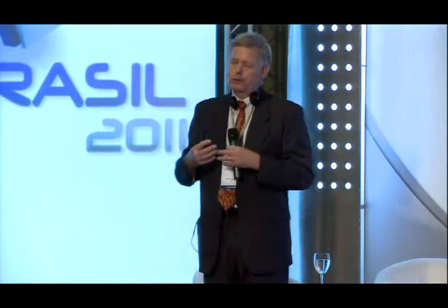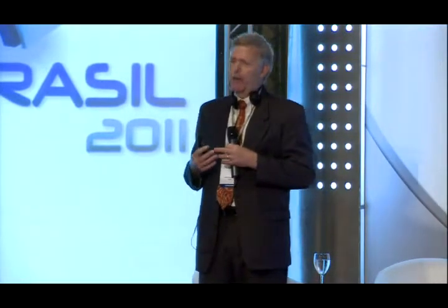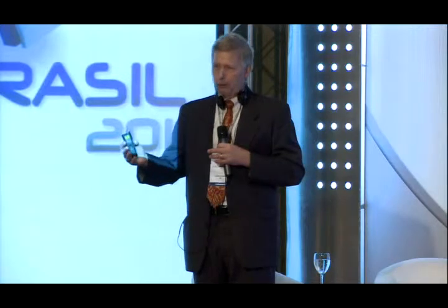That is a functional attack, and it is a signal that we have to pay attention and do some maintenance. In a severe marine environment, it's very usual to have white rust because this is a very corrosive environment.